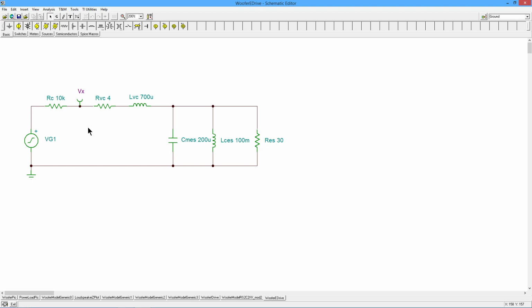Some of the bargain ones, they only go up to maybe 100, 200 hertz before they really start to die on you. So they start to get really inaccurate. You're going to have to spend some money to get a DMM that will give you the kind of accuracy that you want, have enough resolution, up to 20 kilohertz. The scope is the obvious thing to use here.